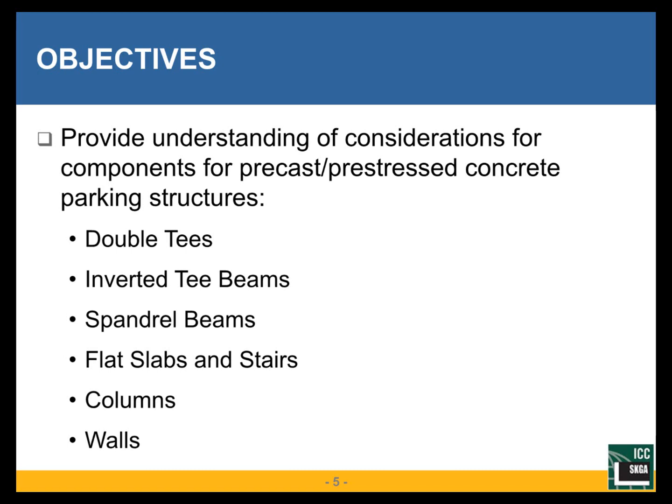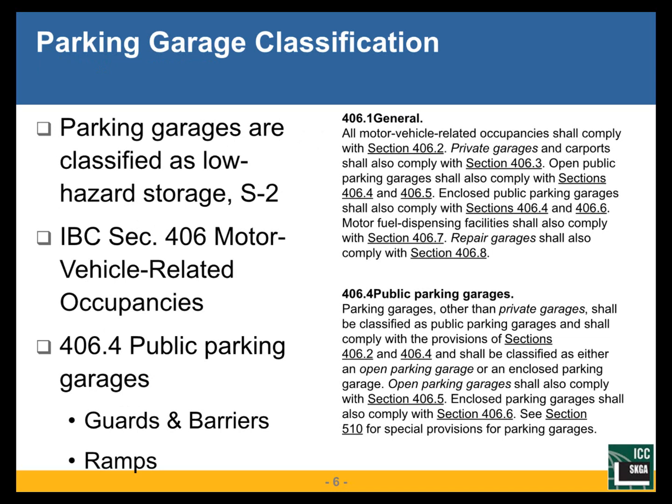for precast parking garages. Parking garages are classified in IBC in Section 406 under motor vehicle related occupancies. They are low hazard storage structures, so before we get into the specialty of parking, we are storage S2.